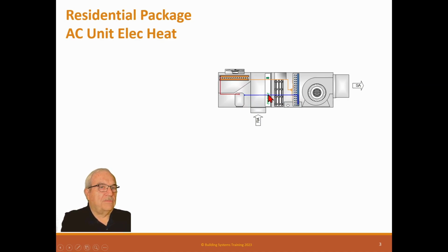So as the gas comes out of the evaporator coil, it's a vapor. It's a vapor with real small refrigerant droplets in it, which carry the heat. And it comes to the compressor, and the compressor compresses it. And as it compresses it, it heats it up. That's part of the physics of matter. If you take a gas and you compress it, you will heat it up. The hot gas goes into the condenser coil, where the air flowing across that coil condenses that gas into a liquid.